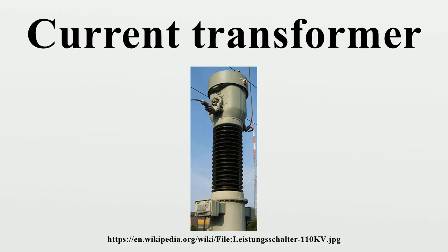The alternating current in the primary produces an alternating magnetic field in the core, which then induces an alternating current in the secondary. The primary circuit is largely unaffected by the insertion of the core. Accurate current transformers need close coupling between the primary and secondary to ensure that the secondary current is proportional to the primary current over a wide current range. The current in the secondary is the current in the primary divided by the number of turns of the secondary. In the illustration on the right, I is the current in the primary, B is the magnetic field, N is the number of turns on the secondary, and A is an AC ammeter.